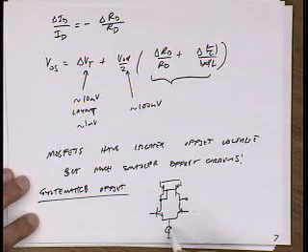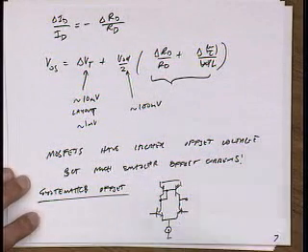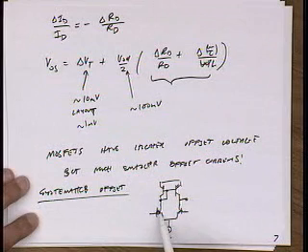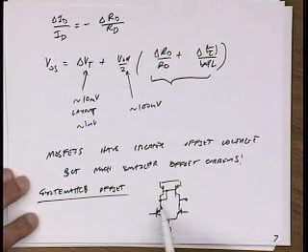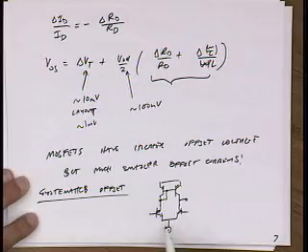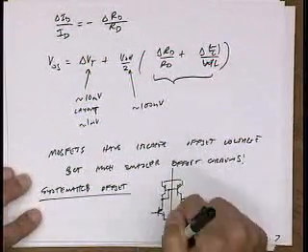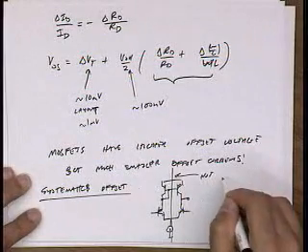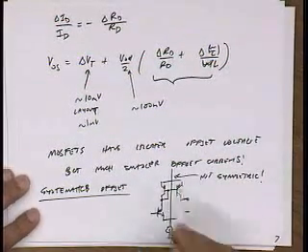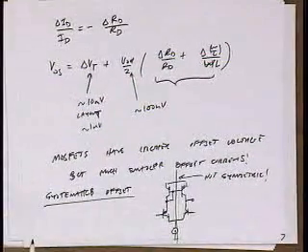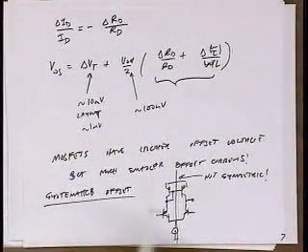So you're saying this current won't split up equally? Evenly. Yeah, that's true. Another thing I could think of is because of the early voltage, right? Their currents have to be different because the VCEs are different, right? This one sees a fixed VCE, this one sees a varying VCE. So basically, this circuit is not symmetric. So even if everything matches, there will be a systematic offset in the circuit. Okay. Questions?